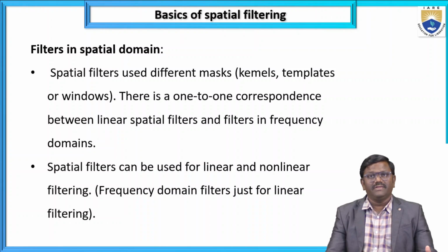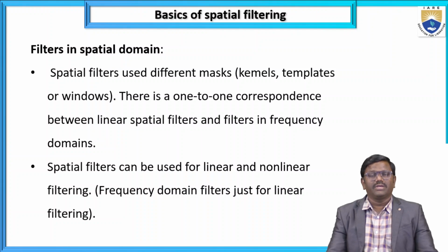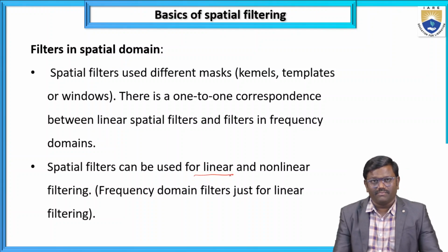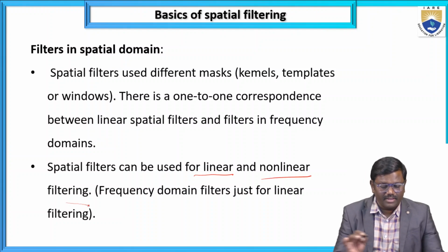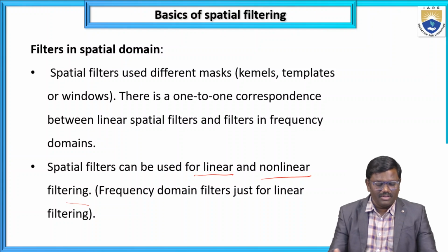There is a one-to-one correspondence between the linear spatial filters and the filters in the frequency domain, which we can understand in terms of time and frequency. Whenever you are using either linear or non-linear filtering, you may consider frequency domain filters just for the linear filters.